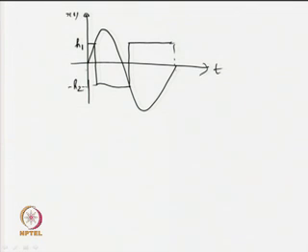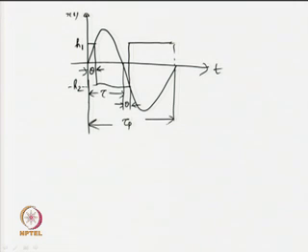Now, as you know, this span is the theta time delay associated with the dynamics of the system, whereas this span we take as tau from here, whereas this span again becomes theta, and finally the period of the output is given by tau p.